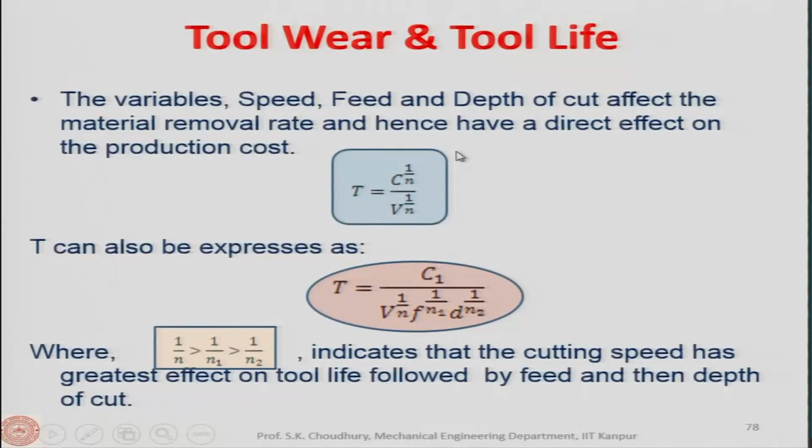As you increase the depth of cut, the tool wear will also be more. So, not only the speed that is shown in Taylor's tool life equation, but also the feed and the depth of cut will affect the tool life.